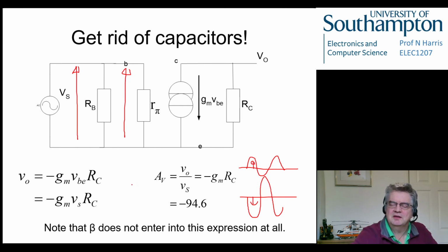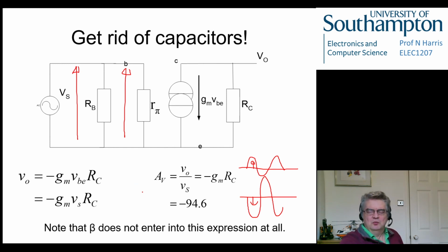So that's quite a neat way of working out what's going on in your system for AC, and we've done quite a lot of abstract stuff there. We've worked out the bias conditions by using a large signal model to work out what the value of the slope is for the transfer characteristic. We've simplified that into this term called GM, so that varies with the bias current, but the bias current is normally fixed.